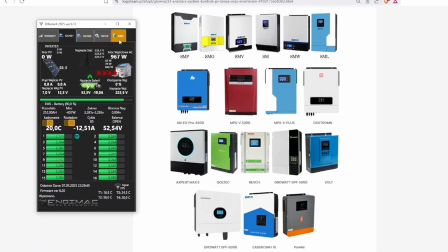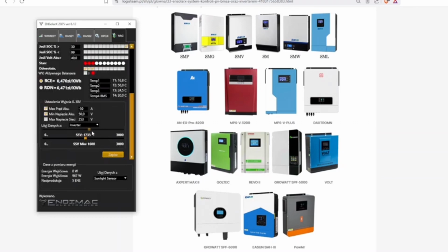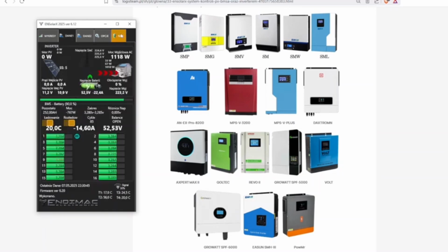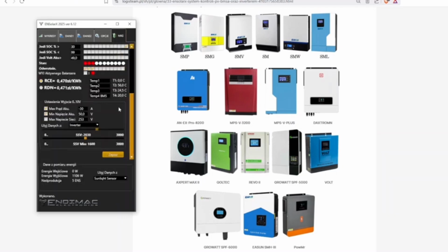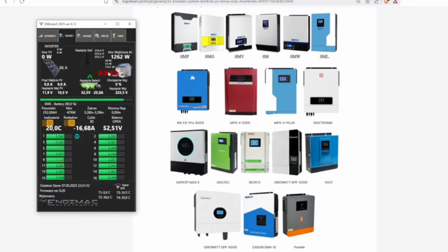Let's give it 18.5 amps. Another reading, because this is a reading every few seconds, 19 amps. We're going to look at this strip, this slider. We can see that 1,700 is going up slowly now, slowly pulling it up. Here we already have 957 watts. We'll wait a moment until it gets to 30 here. We'll rewind a bit so you don't have to wait. Okay, we have 27 amps and we'll get to 30 here in a moment.